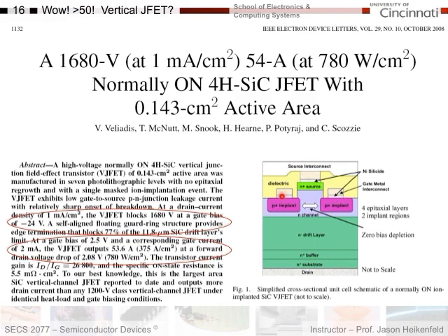Here are my gates. And so what you have here is basically like a donut, that if they reverse bias these PN junctions, it will pinch off the channel here. So this P plus implant area, this gate here, if you looked at it from the top, would look like a donut essentially, and you would get all your current flow down through the center of that donut. And if you put more gate voltage, you would basically reduce the width or the diameter of this conductive channel here.